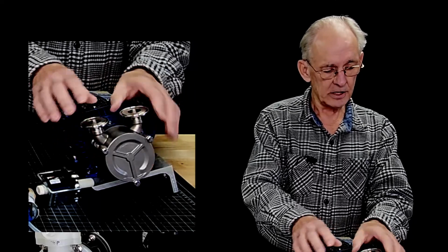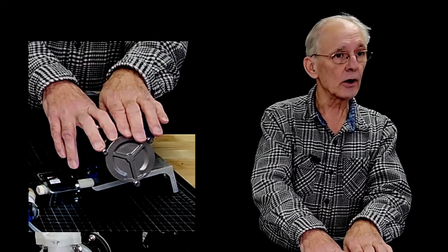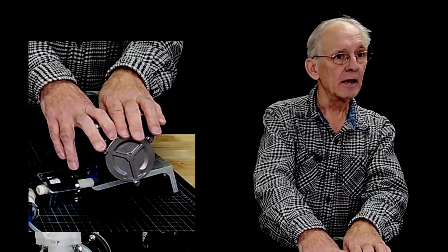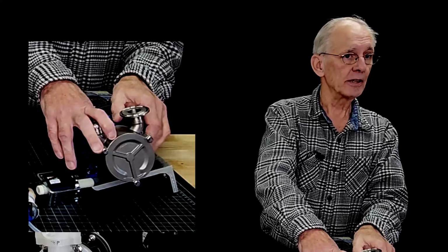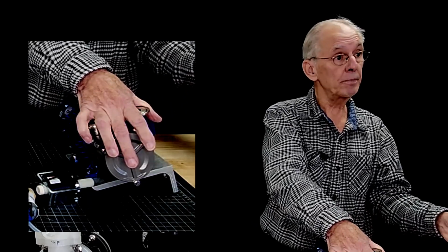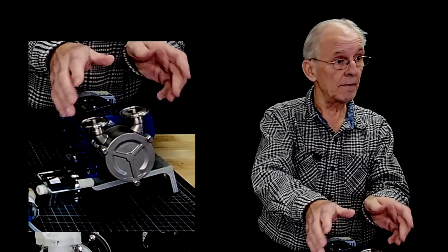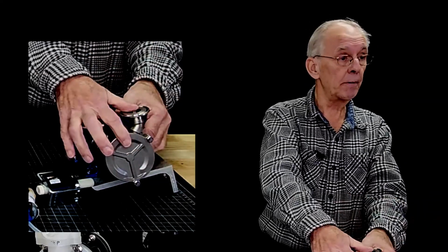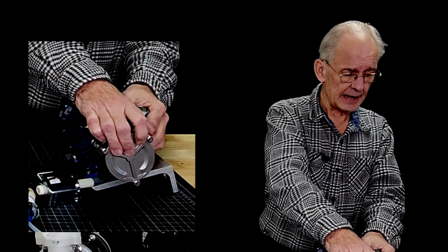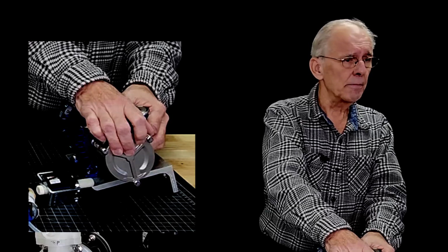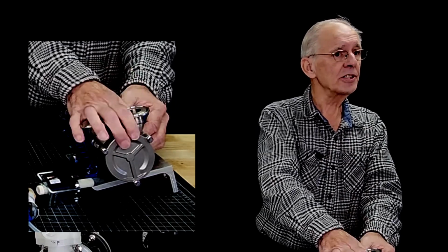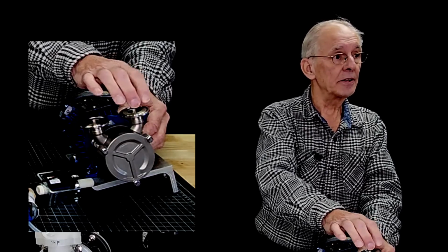So you notice that it has the intake and discharge both on top. And the reason for that is this pump's self-priming, but only if you've put some water in it first. As long as there's some water in it, it will pull air through, and it will pump and expel the air and water out, and eventually you'll get the liquid to come up into the pump. And this can pull water from some 15 feet deep out of a tank. So the unique thing about it is that it's not positive displacement, doesn't have any valves, and it's reversible.